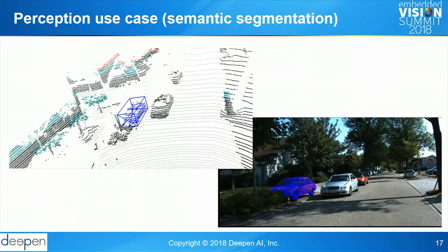And again, if there are some classical computer vision experts in the room, with semantic segmentation, when you can cross-reference what you're seeing on the camera with the points that are being reflected in the LiDAR, that can give you very good accuracy of: I'm seeing a car, that car is over there, that car is not moving. And maybe you even look at the radar to see if the object within that range has velocity of 0 or not, and things like that.